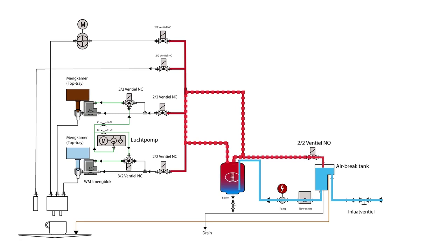The recirculation valve closes. The dosing coil of the cafe milk is actuated and ingredient is being dosed. Shortly thereafter, the two-way valve opens. Water flows to the water restriction receptor and air that is drawn in through the air channel is added. The air pump and the three-way valve at the coffee side switches on. This forces air through the tubes at the milk side. The air removes any water from the air channel and tubes to the mixing chamber.